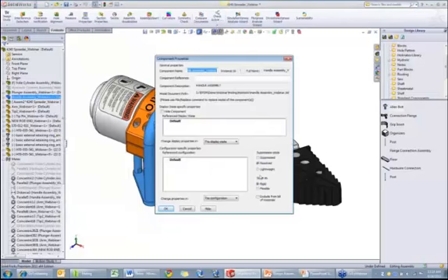You'll have the ability to solve that as a rigid or a flexible object. And this works great. Just make sure you know that flexible subassemblies are very heavy inside of your main assembly documents. So only use this tool when you absolutely need to have that motion in your design.